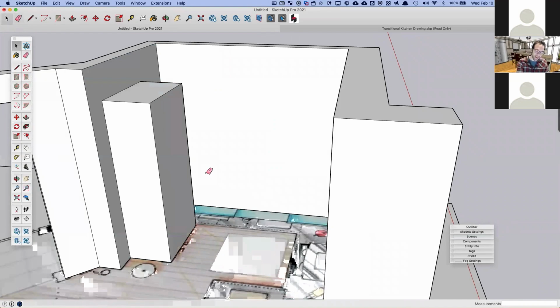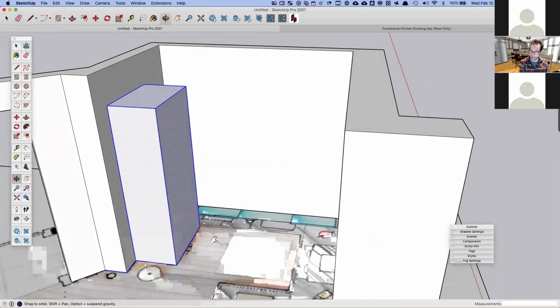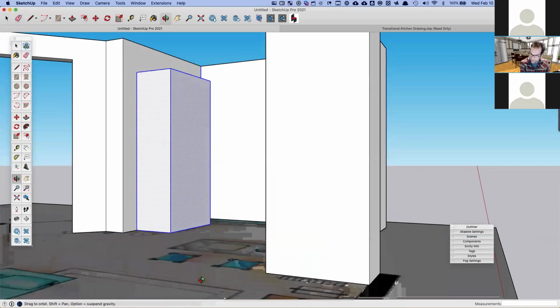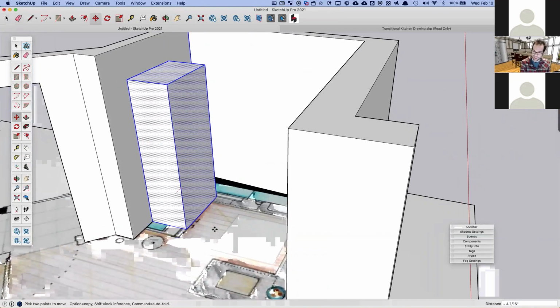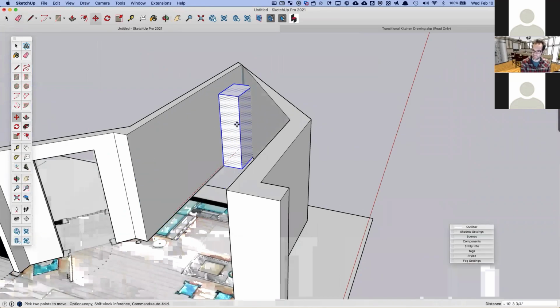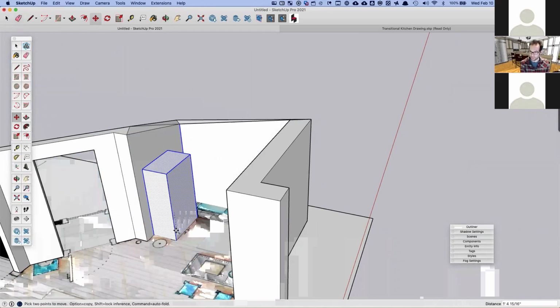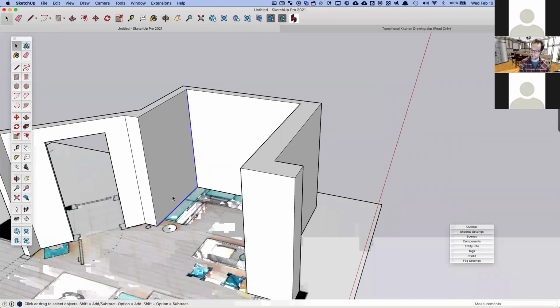And you might go, all right, maybe I can just highlight this whole thing and move it out of the way. So you try to highlight it all, and maybe you get it selected just right, and then you go to use the move tool, and it's kind of stuck, and then your walls get all messed up, or something crazy like this happens. This is bad. This can be frustrating if you don't know how to deal with it, but luckily there's a super simple way to deal with it. So I'm just going to undo all the way back.